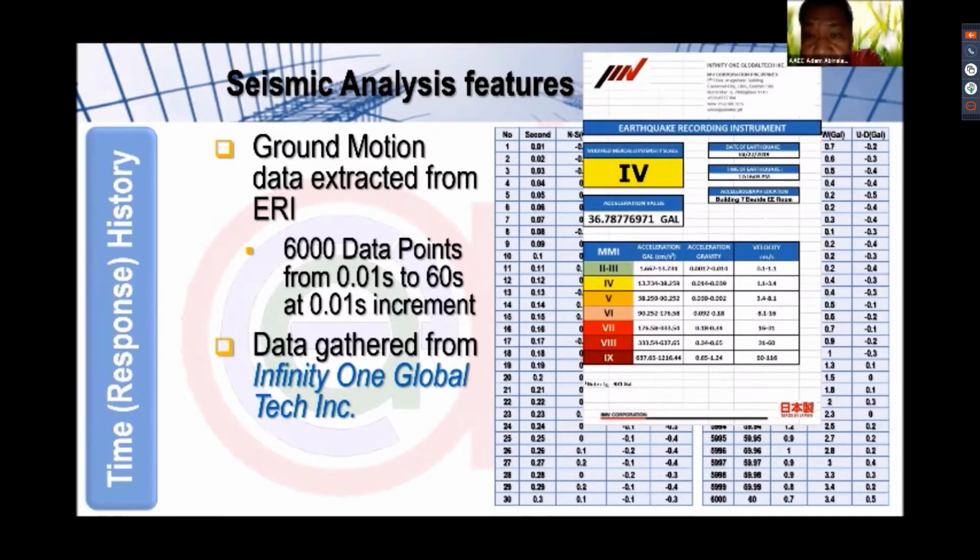So if you look at this ground motion, 0.036 g, it's way below the minimum ground acceleration, or peak ground acceleration, that we use in our design. Considering Metro Manila is in zone 4, the minimum ground acceleration that we use in our design is 0.4 g. So we do expect that this building would respond and perform well during that event. Anyway, this gives you an idea of the intensity scale at that particular location of the building, which is intensity 4.